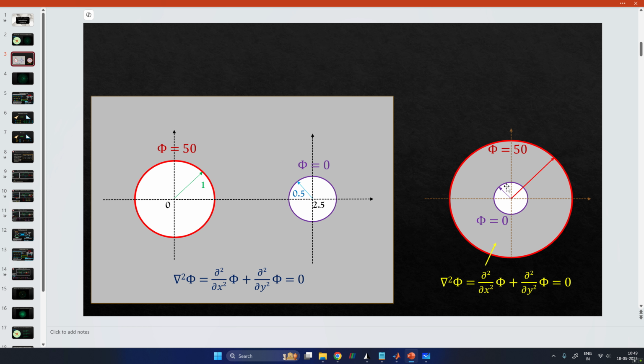This is a bit like a coaxial cable problem, you could say, where you're trying to solve for a capacitance. You can solve it and then just map it back. Here you could solve it in radial coordinates, and this analytical solution can be mapped back. And due to this analytical solution, we can easily compute the flux that is leaving this circle and the flux that is getting into the other circle.